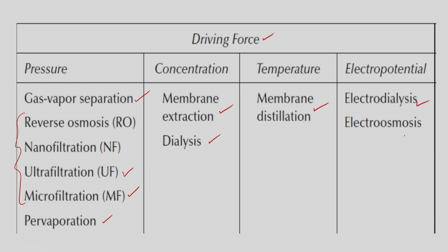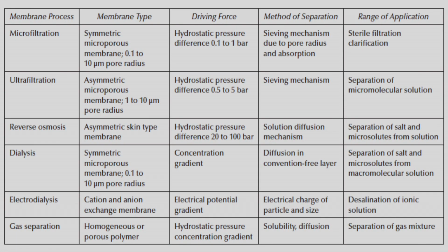Electropotential, electrodialysis, electroosmosis; probably we are going to see a little bit about electrodialysis as well. So, this gives you the overall picture, right. Microfiltration, ultrafiltration, reverse osmosis, dialysis, electrodialysis: where it is used, what the membrane types are, whether it is a symmetric membrane, what the porous nature is, and what the pore radius is. Pore radius we have already seen.